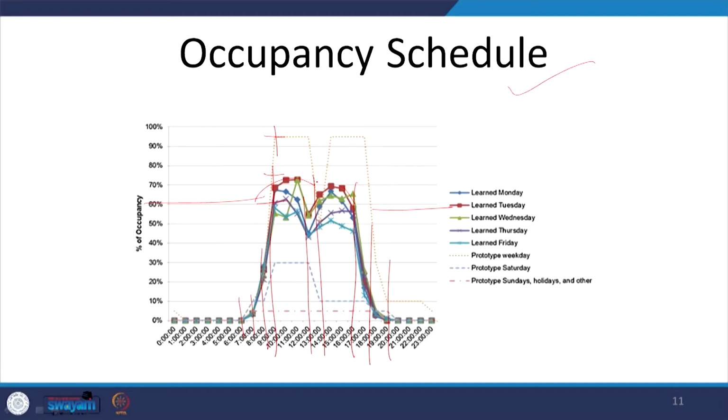One, the occupancy is a big contributor to the internal heat gain, internal heat load. So, that is what it adds to. The second, in case we are using sensors, we can also optimize the use of sensors to optimize the lighting loads and the ventilation loads, HVAC loads.